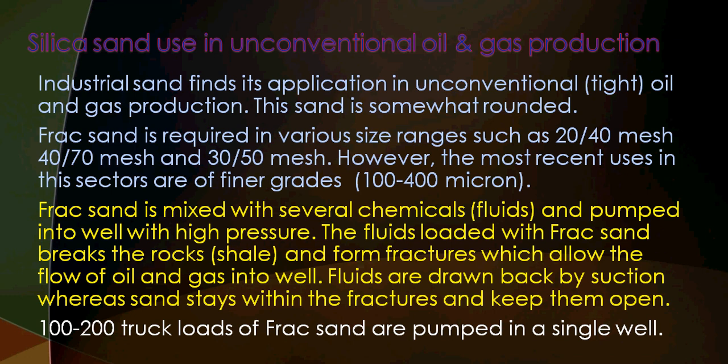So frac sand is required in various size ranges such as 20-40 mesh, 40-70 mesh, 30-50 mesh. However, the most recent uses in this sector are of fine grades, so even from 100 to 400 microns are used. Frac sand, I have already explained it to you. This is important, and I should give you some idea that in a single oil well or gas well, 100 to 200 truckloads of frac sand are pumped.